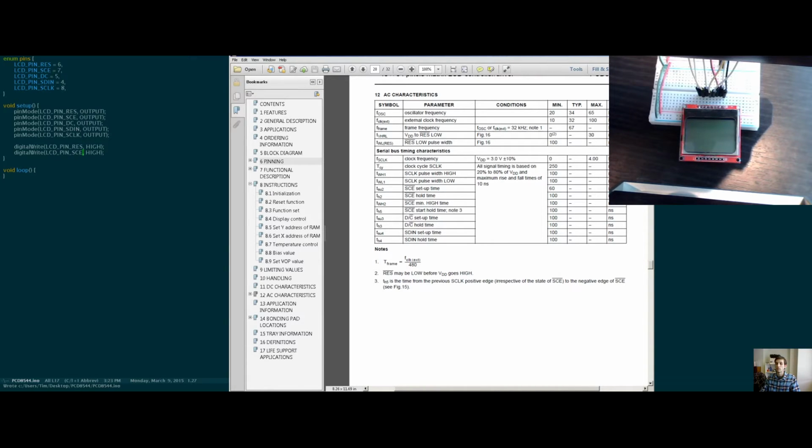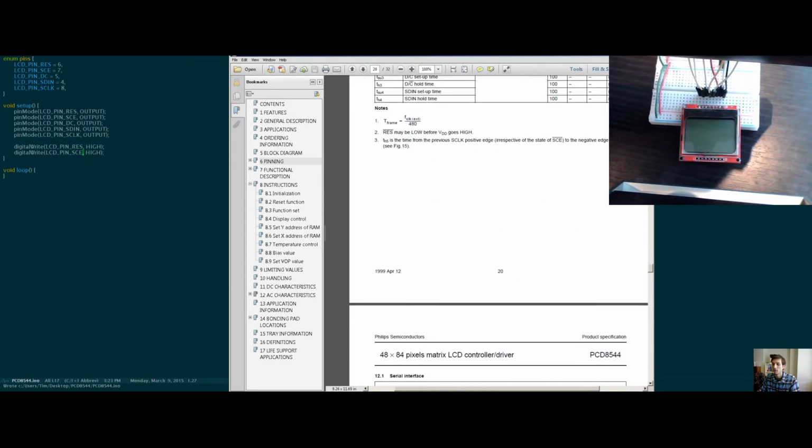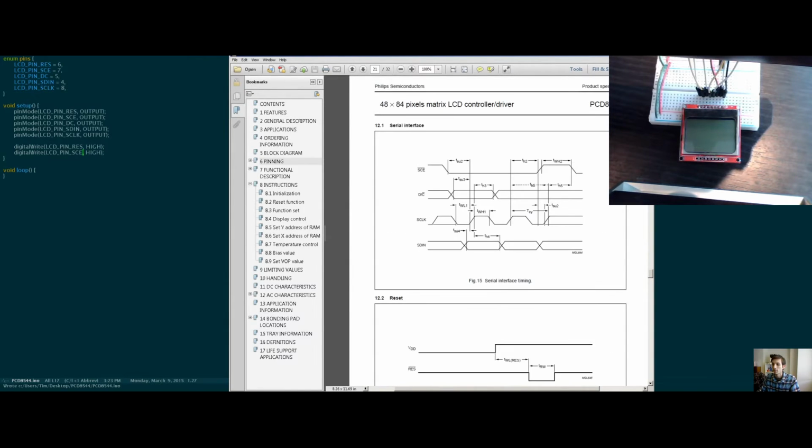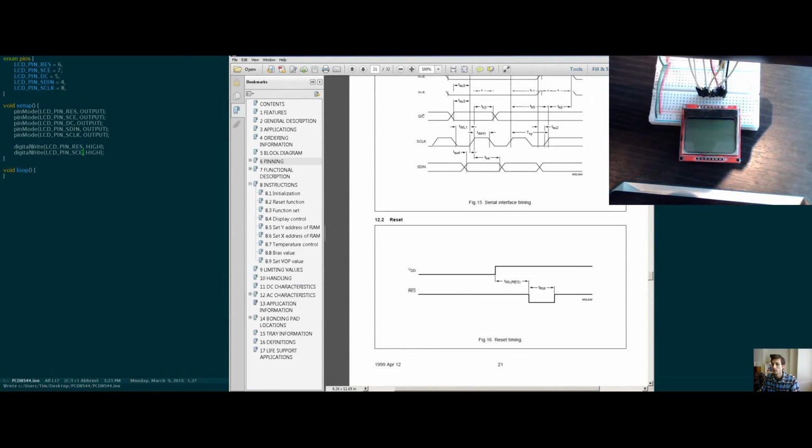And we can't really do any delay shorter than 1 microsecond accurately with the Arduino, but having a bit larger of a width is fine. And the microsecond is so fast anyway, we're not going to notice that in our code. So then this is just a bit more looking at that a bit closer.